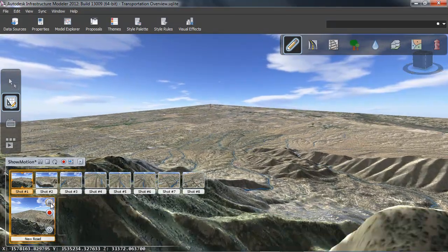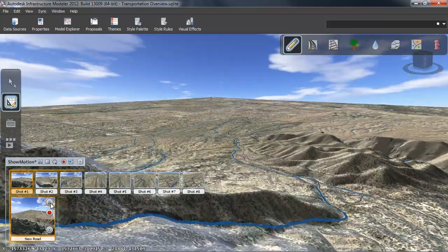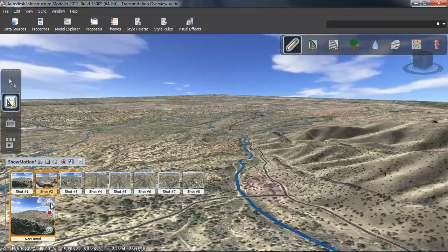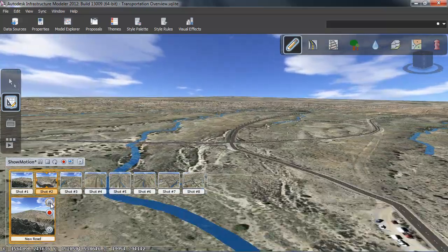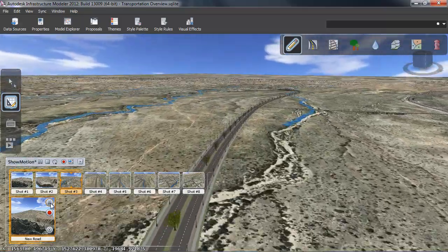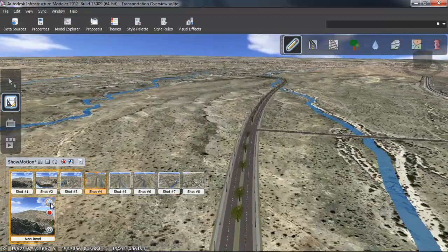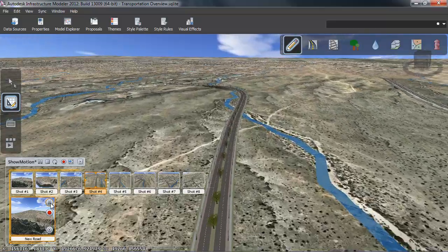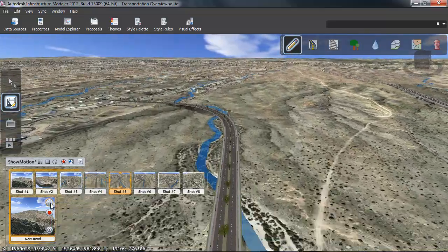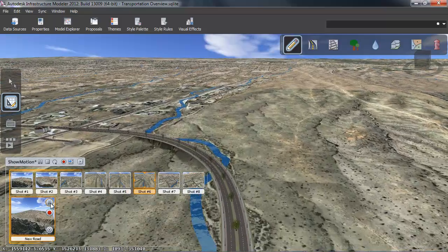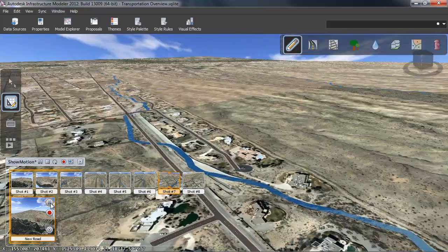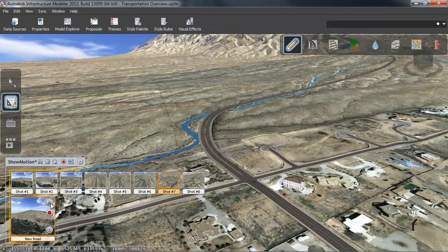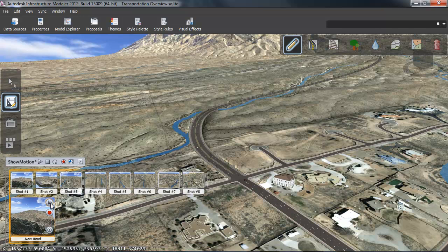And you can already tell how the roads are already fully rendered in the background. And as we move in here, you'll notice all the trees and all the light poles and everything is already fully rendered. So a lot of times what I do is when I get ready to play or record my videos, I'll turn my level display on to high, and then as soon as I'm done rendering the video, I'll turn it back off so that I can move around the model quite a bit faster. It's easier on the software and on your computer if you turn your level display off.